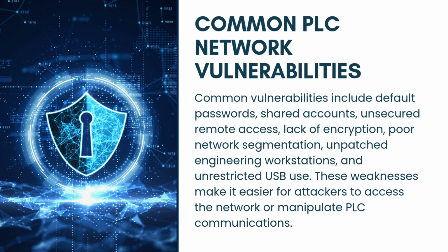Now let's identify some of the most common weaknesses in these networks. Common PLC network vulnerabilities include default passwords, shared accounts, unsecured remote access, lack of encryption, poor network segmentation, unpatched engineering workstations, and unrestricted USB use. These weaknesses make it easier for attackers to access the network or manipulate PLC communications. Many of these problems are not especially advanced. They are often everyday issues caused by weak practices or poor security controls.